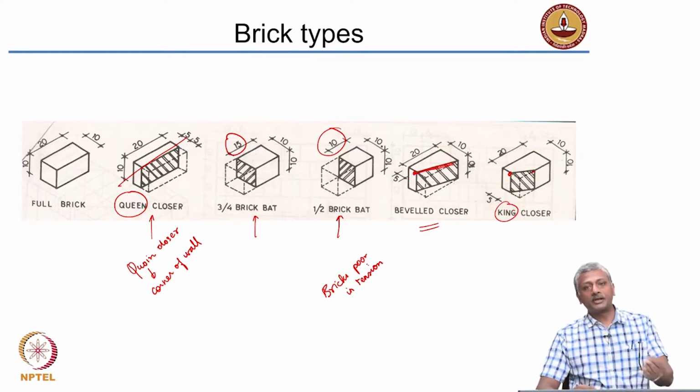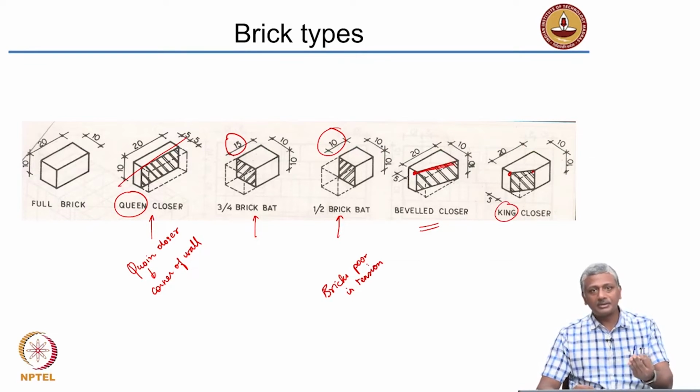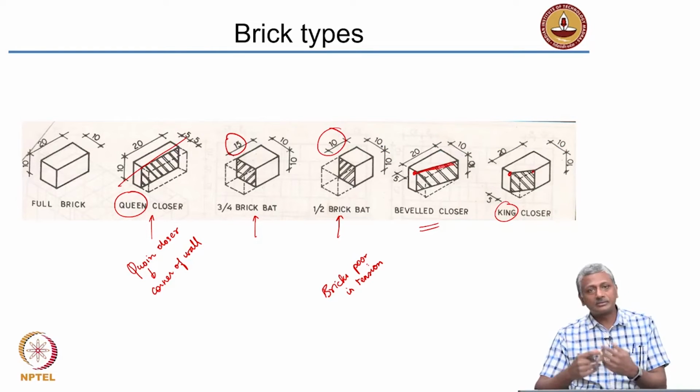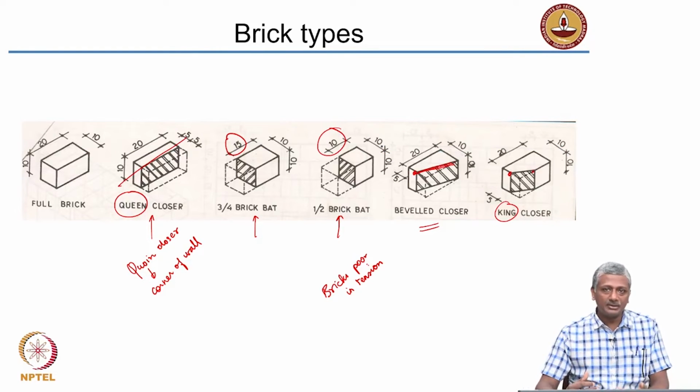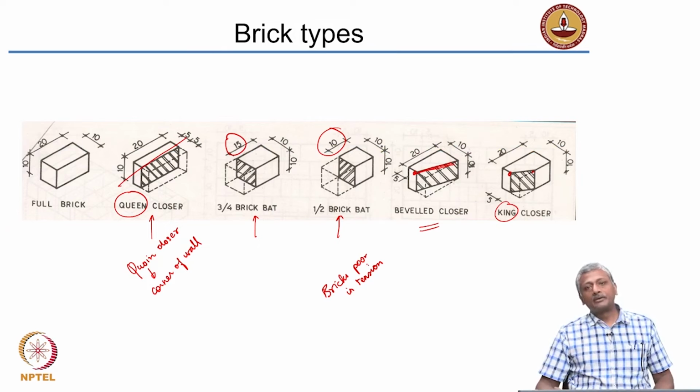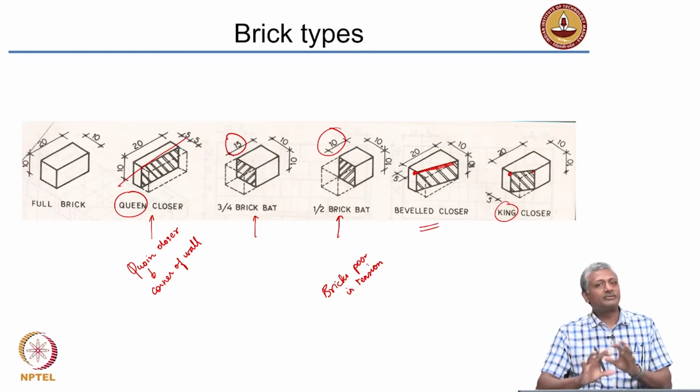Most construction materials, brick, stone, concrete, all these materials are very strong in compression but poor in tension. Steel, of course, is as strong in compression as it is in tension. One material that is opposite is wood, which is a lot stronger in tension, especially when you are going along the grains of the fibers in the wood, as opposed to compression. So, wood is stronger in tension than in compression. Different materials have different types of attributes, and you need to use them correctly.